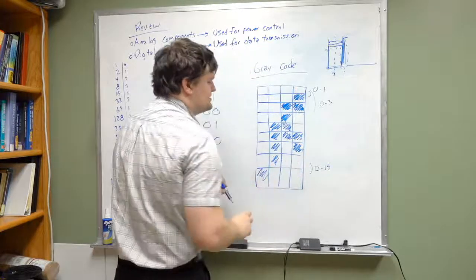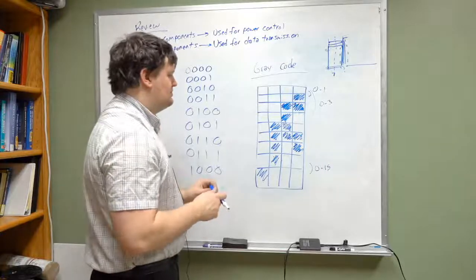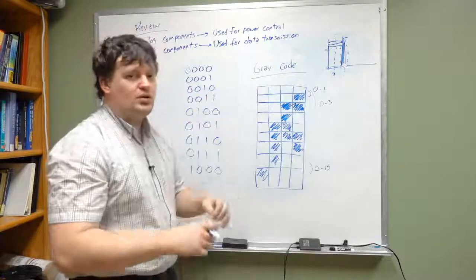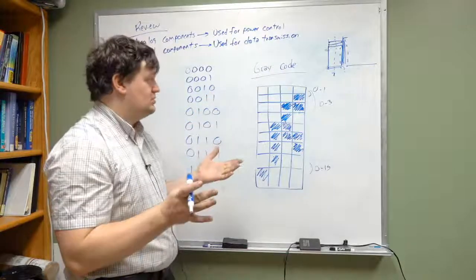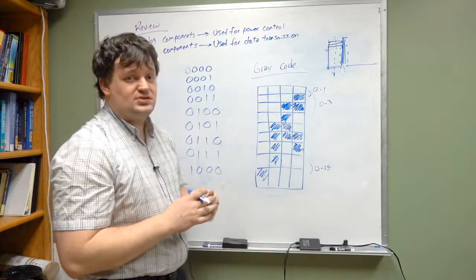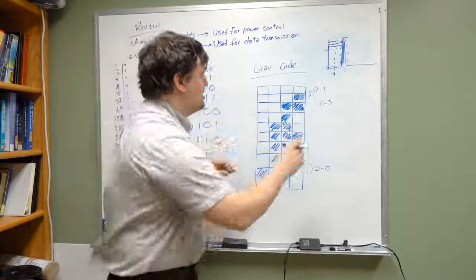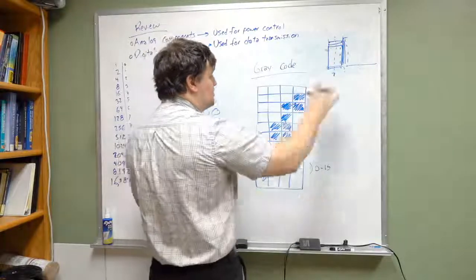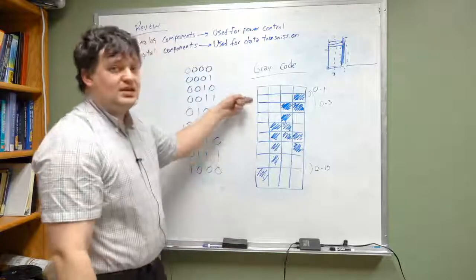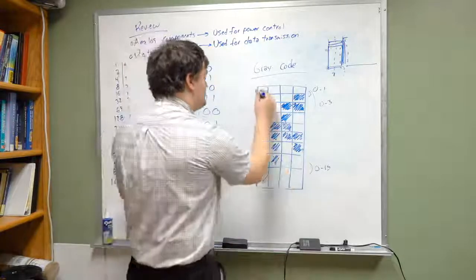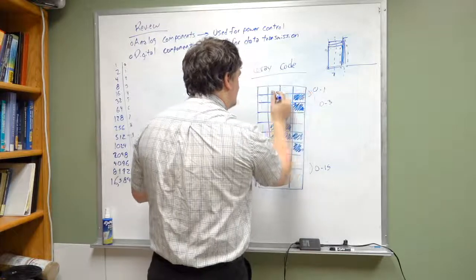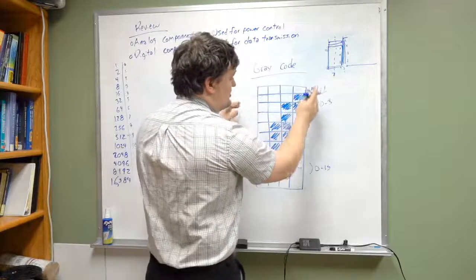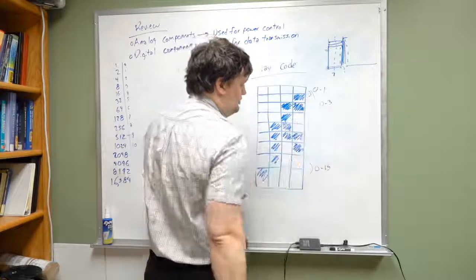And that's the essence of what gray code is. I don't know if I'm doing gray code justice, but in each one of these, you only have one switch. That's all. It's not 2 switches, it's 1 switch. So trying to read the difference between these two, you either get this one or you get this one. If an error occurs, if you're reading on the transition, you only get one value. So here, if I were to read right here, I would either be getting a 1 or a 0. Similarly, down here, I would either be getting a 1 or a 2.